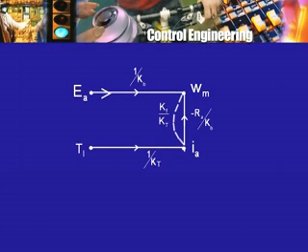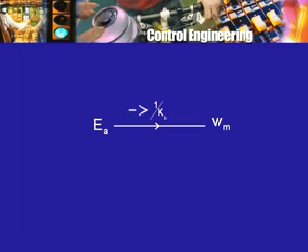In this case, we do not allow such a thing. The rule says that by path we mean something where the same node will not be visited again. So EA to omega m is okay, but EA to omega m to IA to omega m is not to be chosen. That is the way the rule is, because that is the way the determinant expansion will have it. So we are not to do it that way. So then what are all the paths from EA to omega m? There is only one, namely this edge 1 by kb. And so with that forward path, or with that path from EA to omega m, we have a single transmittance 1 by kb.